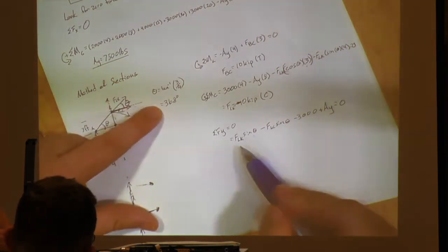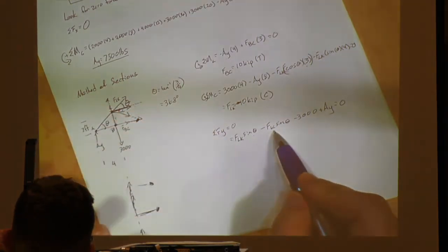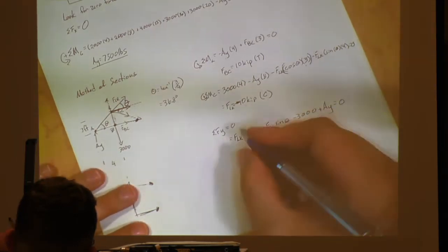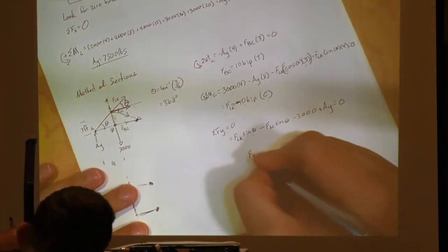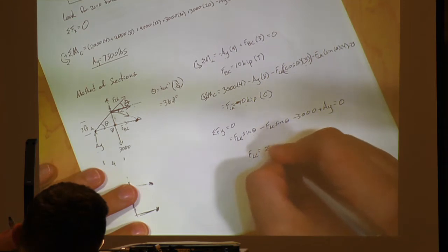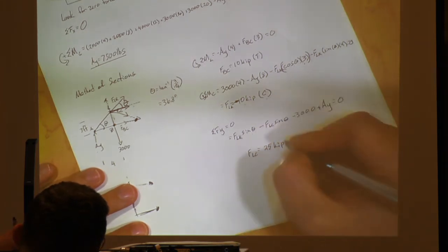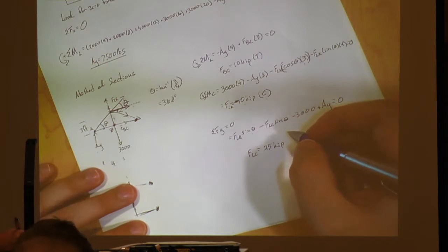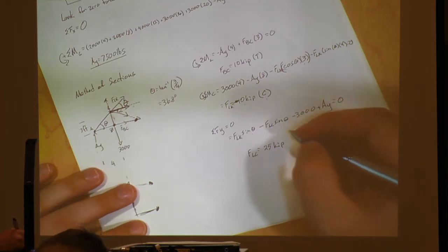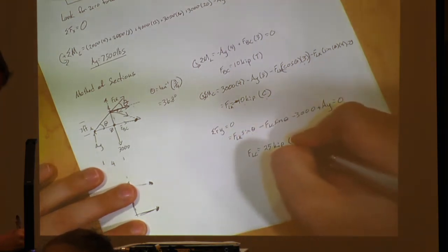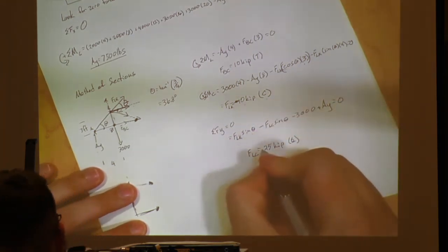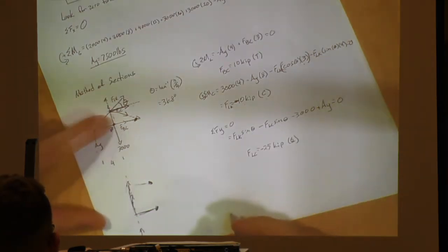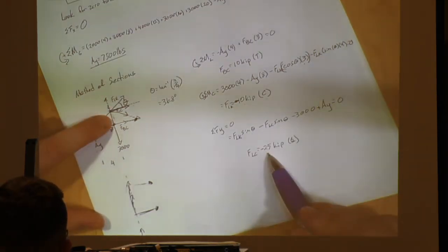Theta is here again, FLK is here, and we're solving for FLC. So FLC is going to be 25 kip. Tension or compression? You've got a 50-50 chance, man. It's compression. All right, and I don't update my free body, so I just threw a negative in there.